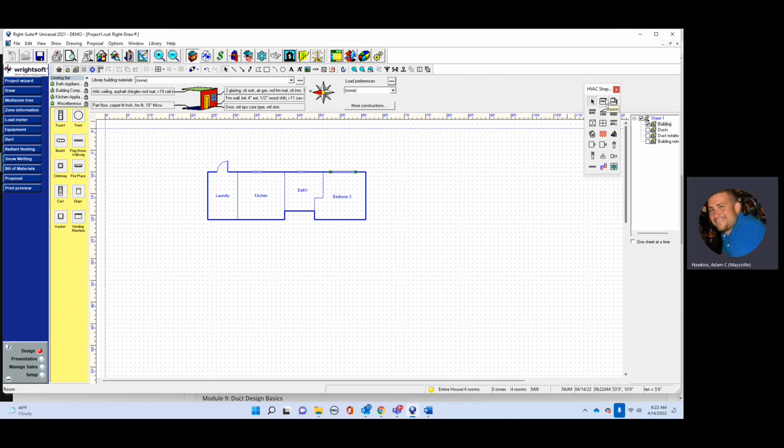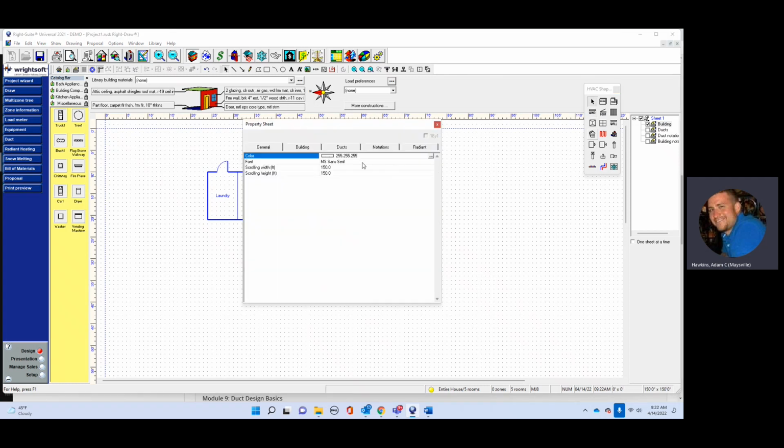We're just going to draw that as a square, and then we'll take care of those closets in the hallway different. So this room is 14 by 10. So it's a little bit shorter this way. 14. And it has windows on both sides, and they're both A windows. First one is 51, so I'm just going to stretch this out 4 feet and then right click it.